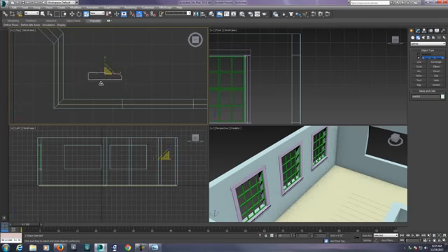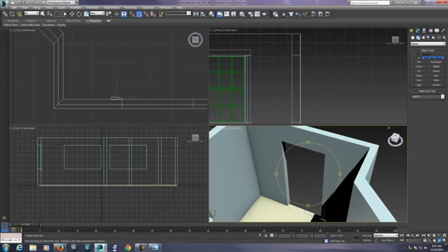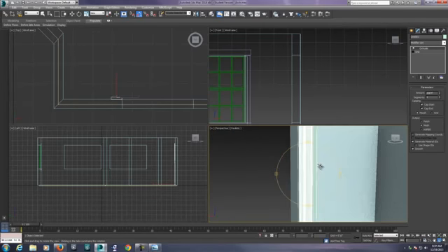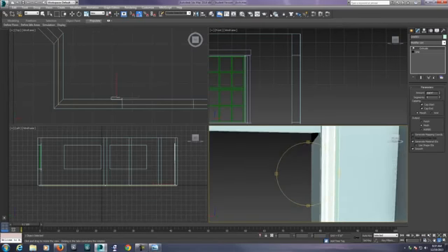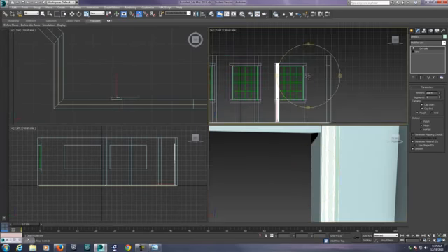I'm going to scale it down so that it's right on the inside of the door frame. I'll put it on the base of the floor there. And now I'm going to swing around here and show you what I get when I extrude. There's a nice door casing here that allows me, when I do a render, let's see if we can get in there, and I hit the render button, you'll see that this door frame has a nice casing on it. And you can use this for your windows, your doors, your baseboard. The technique is crazy here. You can just do about anything.